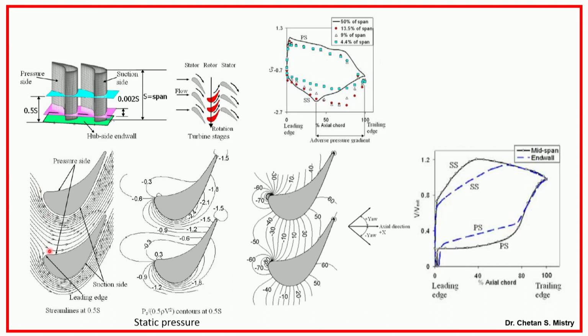I will have a stagnation point placed somewhere here, and from that stagnation point the flow moves towards the pressure surface and towards the suction surface. Because of the shape of the passage, the streamlines converge, which gives acceleration. Okay. Now, if we plot the CP distribution, this is representing my CP distribution.